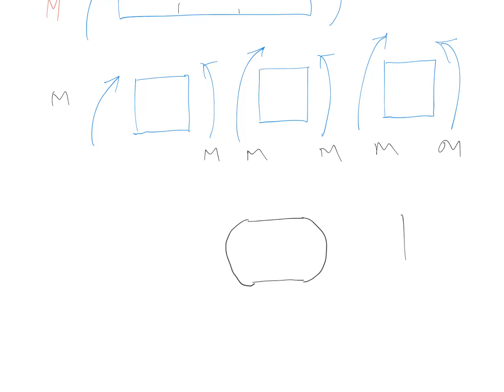What happens if this element behaves in this way? Since the other 2 elements are undergoing the same kind of loading, they should also exhibit the same deformation behavior. Let me draw the deformation for the other 2. It should be the same, isn't it? The planes bulge out in a similar manner because the moments are the same.